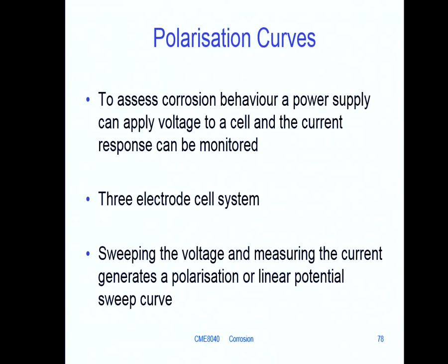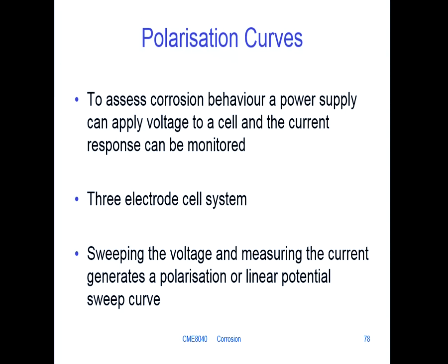You're going to look at its potential current response, so you're going to want to measure the potential on that bit of steel, and that means using a reference electrode and, if possible, pointing that reference electrode so that its porous frit is pointing towards the surface that you're examining.